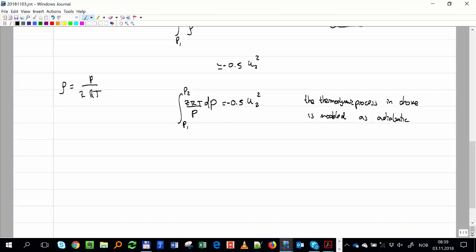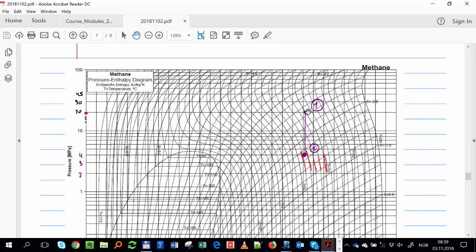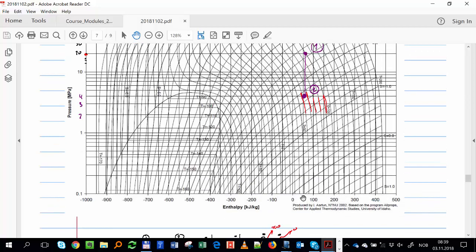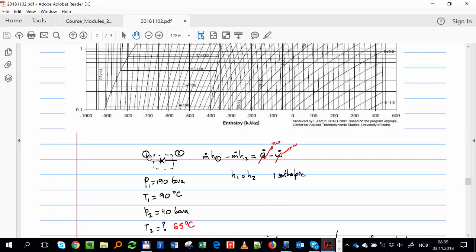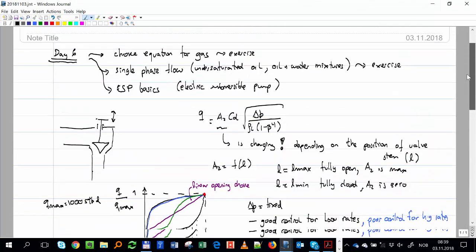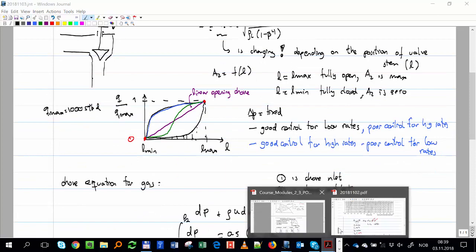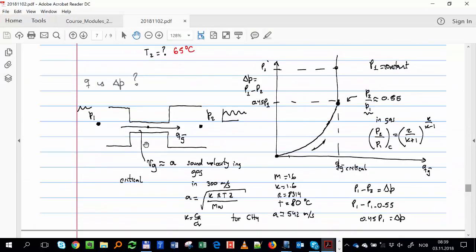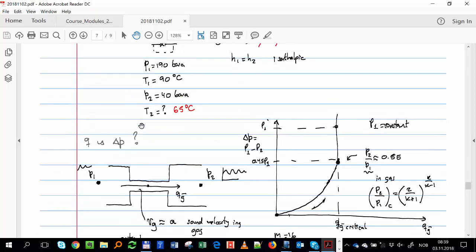And you told me, well, you were assuming that it's isoenthalpic, right? In this exercise we did yesterday. So why don't we have the same assumption? Remember, here this is between the outlet and the outlet of the choke, when the velocity has increased again. If I want to make it between these two points, then the kinetic energy cannot be neglected. You have to include it. The enthalpies between these two points are not the same because you have the kinetic energy.